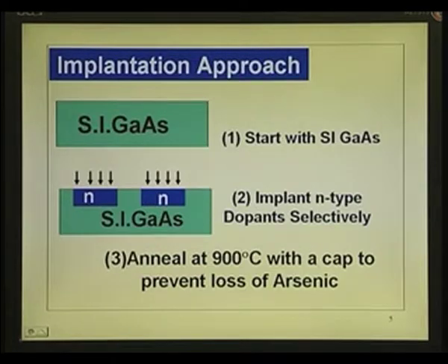The atoms come in the form of ions, but when it comes and implants on the wafer, the path for the beam is in that direction, ionized path, but it is neutralized. It does not remain as positively charged, it is neutralized by electrons coming from the back door. So, current flow is like that, path complete. So, you have the electrons coming in neutralizing that. So, what you have finally, even though you are implanting ions, what you have finally is the atoms themselves, neutral. Because there is one question which sometimes people have in mind, that is I just mentioned, there is electrons coming from the back side. So, you have this N region which is implanted, and each one of them is isolated by this, perfectly planar.